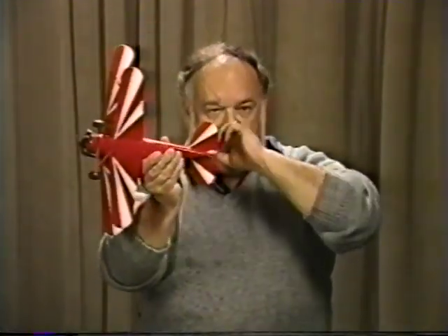We have another situation you have to think about, and that is stick-free and stick-fixed stability. When you're flying along with the airplane and you take your hands off of everything, feet and hands off, the rudder will just free float. It will just sit there, and if the airplane yaws, the rudder will just sort of trail along with it. When you're flying along, the ailerons will just sit there and float behind. Your elevator will do the same thing.